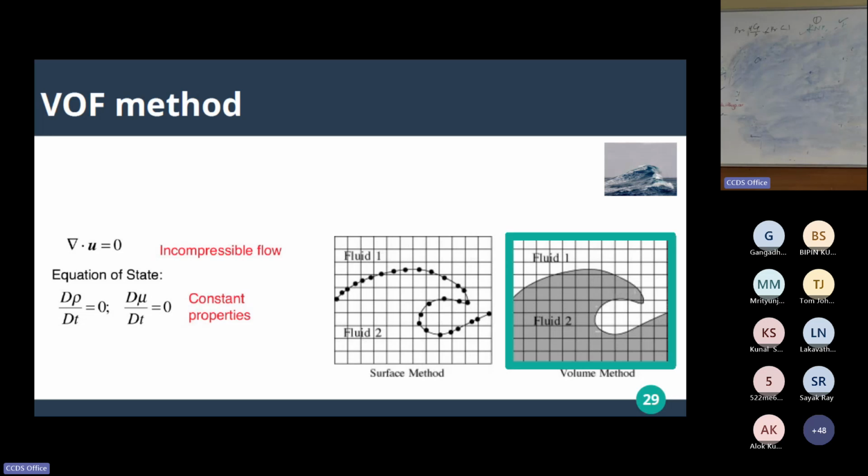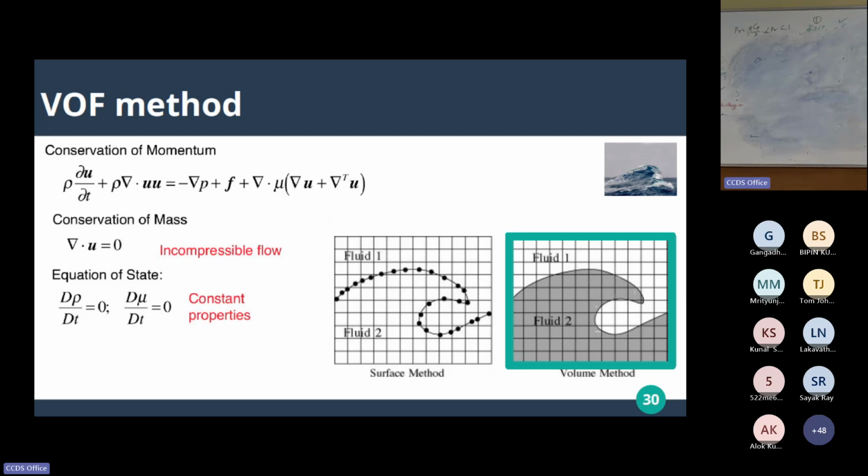That kind of approach, at a very abstract level, is what we call the volume of fluid method. You don't track any interface. You fill liquid, and how that liquid color, in some sense computer language like alpha 1, 0, is happening. Based on that, locally estimate the surface tension force like a volume force, and add that to your momentum equation. So you will have your typical Navier-Stokes equation.